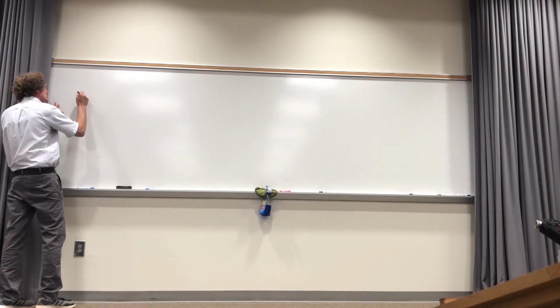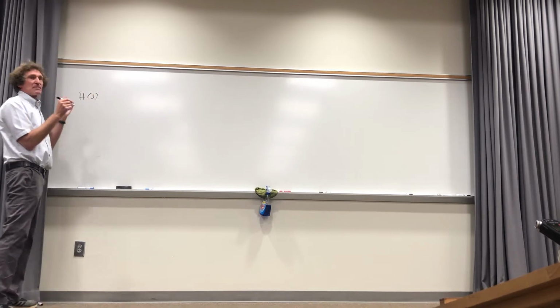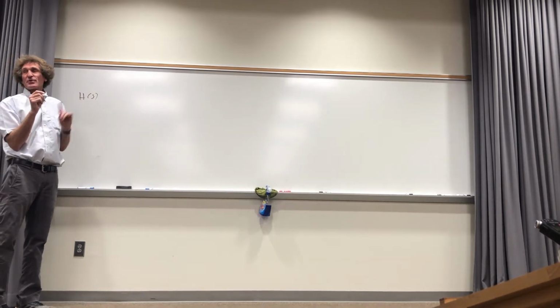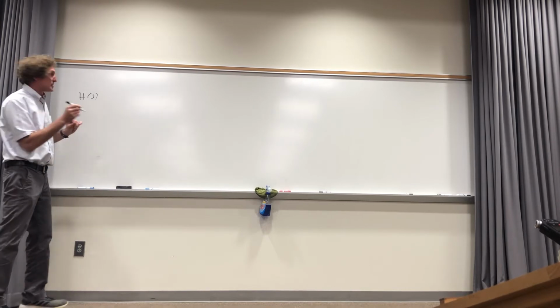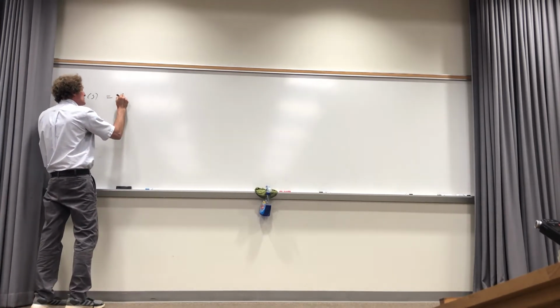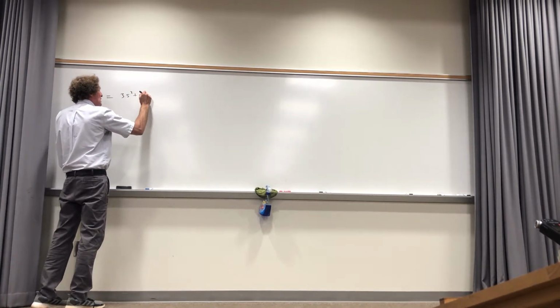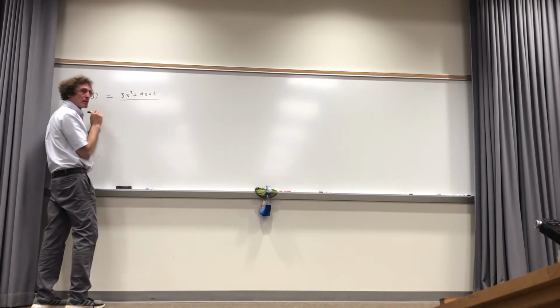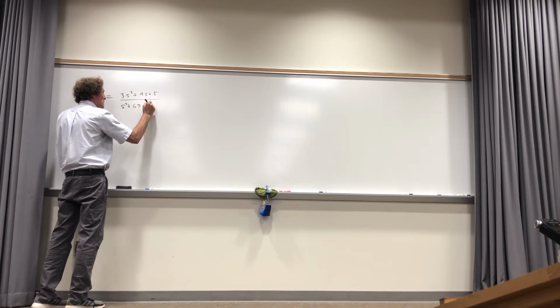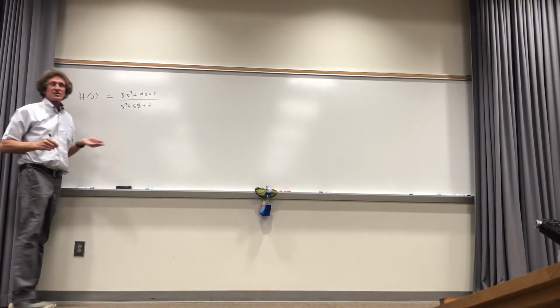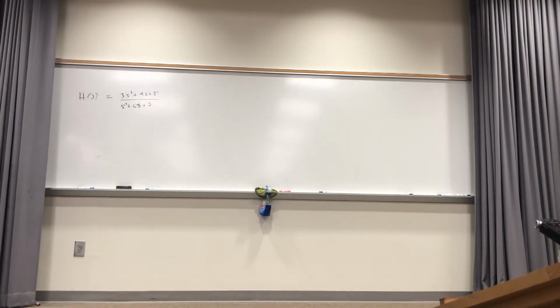He has this. We're going to use op amps to do this. Matter of fact, we're going to have some fun with this. We're not just going to do this, we're going to do this with a digital filter as well. Go ahead. 3s squared plus 4s plus 5, all over s squared plus 6s plus 7. Now, I want to tell you that's a standard transfer function. Two polynomials, second order on top, second order on the bottom. Very easy to understand what that is.